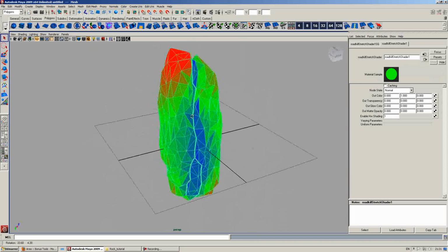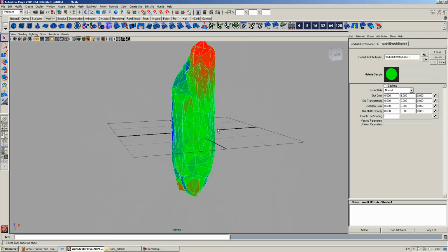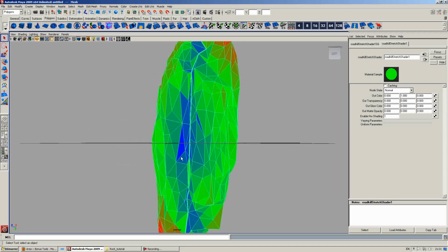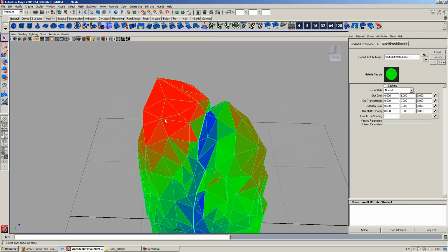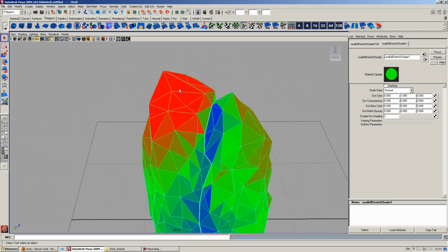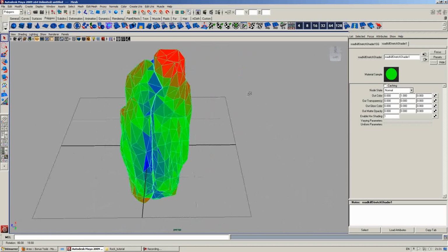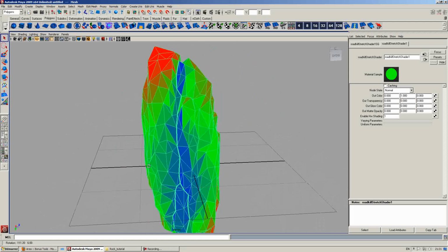While I'm using Roadkill, the green parts are the normal parts where the texel density is normal. The blue ones show you where the texel density is higher than it should be, while the red parts show where the texel density is very low, and this is where the blur is going to occur. So you really want to have a mesh that's going to end up being generally green. That will show up when you apply the shader.